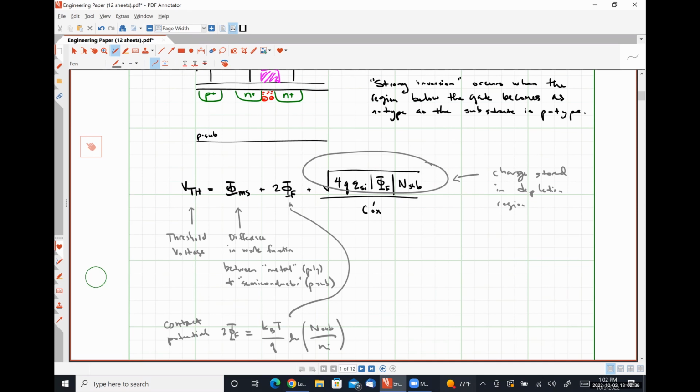And then we have to take into account the contribution of our free charge carriers, which is where our contact potential comes from. And then we have to take into account the difference in work function of the metal to semiconductor junction, which is effectively telling us how much our bands bend to accommodate all this, if we were looking at an energy band diagram, okay?